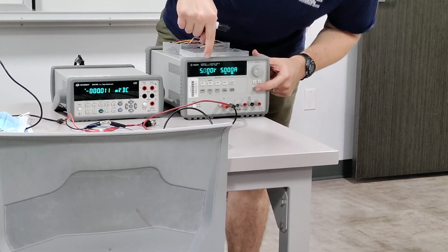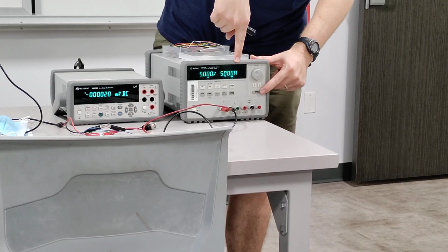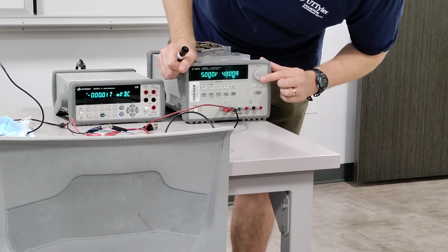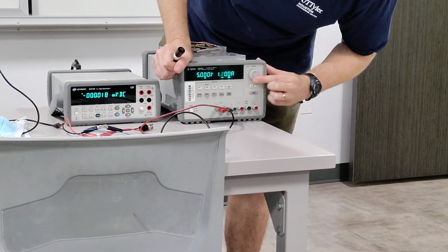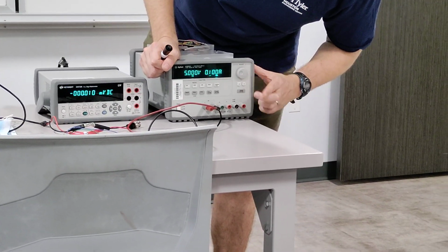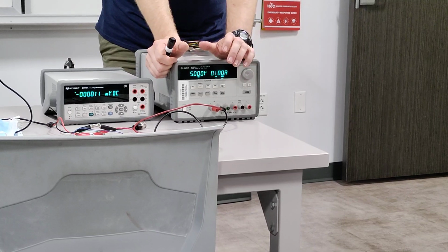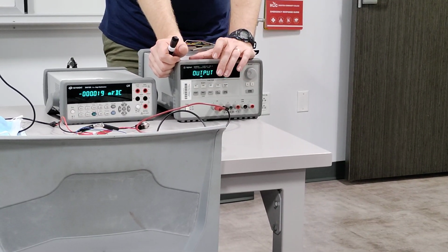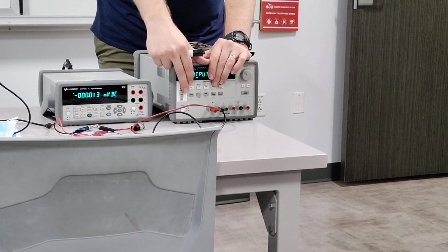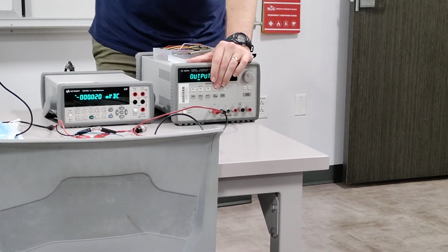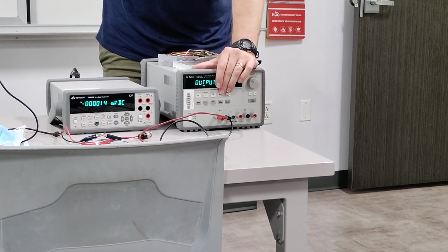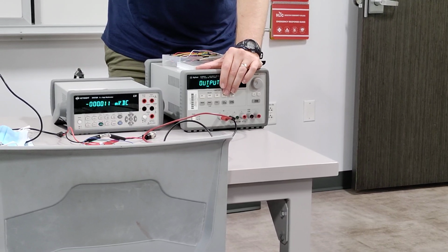You can see it's flashing on the voltage side here, flashing on the current side now. Almost always, we're going to drop this to 0.1 amps or 100 milliamps. That will save us if you short-circuited something. It'll only provide the 100 milliamps. It won't provide the full voltage if it hits that wall, where it would be much more than that otherwise. Does that make sense?